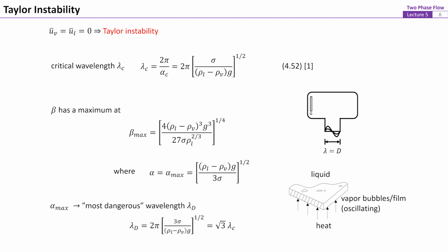One example in daily life is that if a jar containing liquid is put upside down with the mouth open, the interface of the liquid to vapor at the opening becomes unstable more easily with a bigger mouth. In later lectures, the concept of Rayleigh-Taylor instability will be used for analyzing the stabilities of the liquid-to-vapor interfaces and the associated heat and mass transfer in boiling processes.